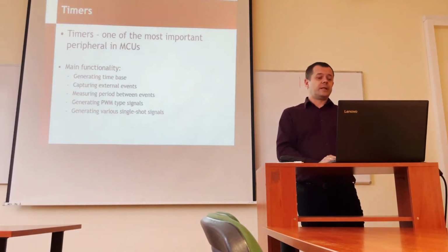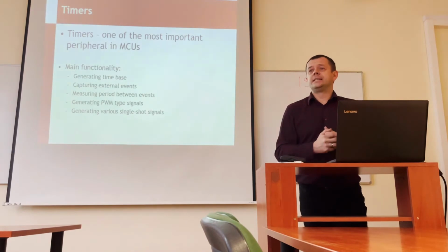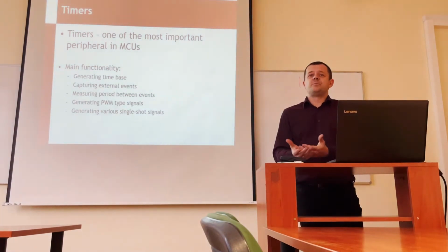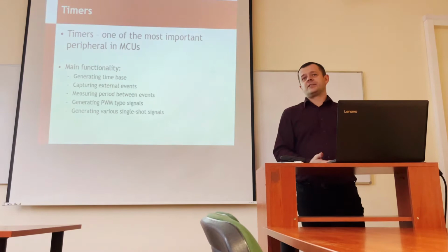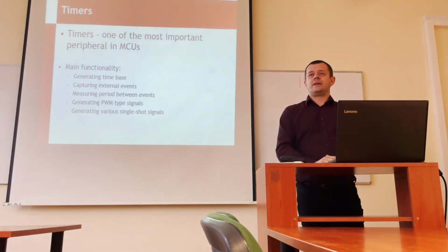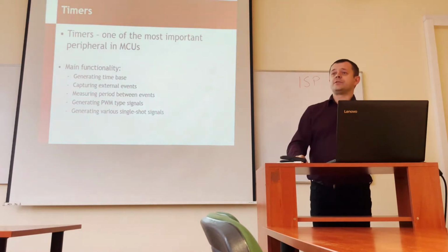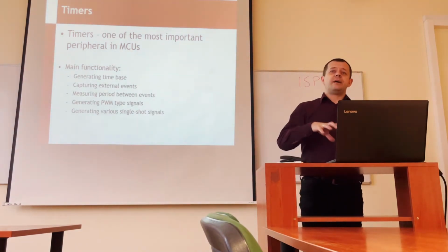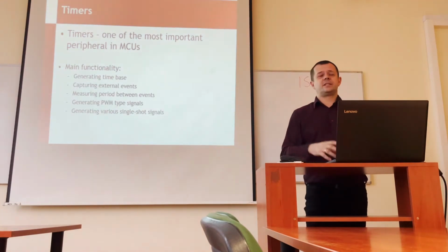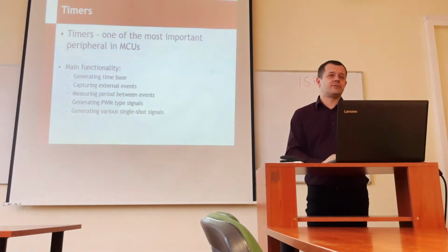Of course, we can do it, but this is so simple that there is absolutely no sense in using the processing power of the CPU itself to do such stupid stuff like counting pulses, generating some repetitive signal or generating a time base. For this purpose, people have integrated the timer blocks, the timer peripherals, into the structure of the microcontrollers.